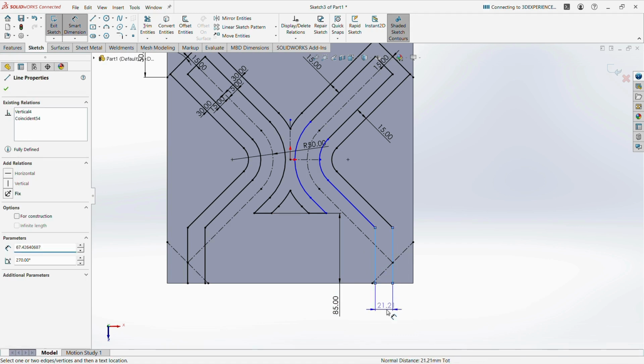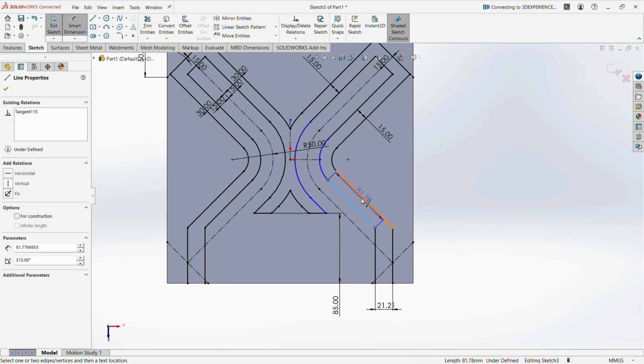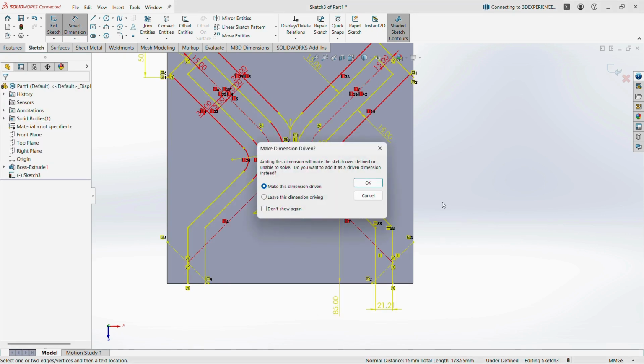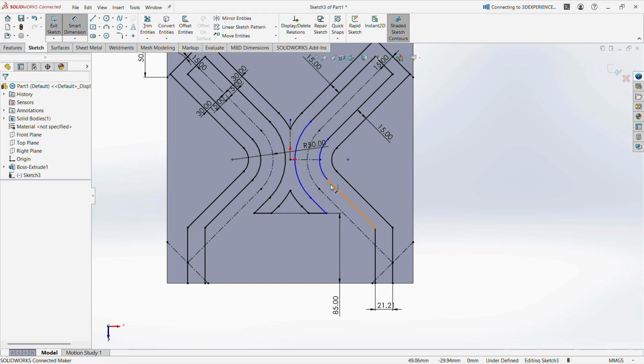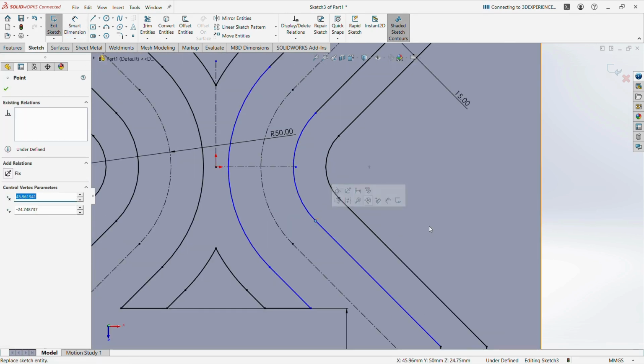Again, choose the smart dimension, then fix this with this horizontal dimensional constraint. It is almost the same value as the left one. Instead of picking the dimension from the bottom one, first select this point and initiate a tangential constraint.